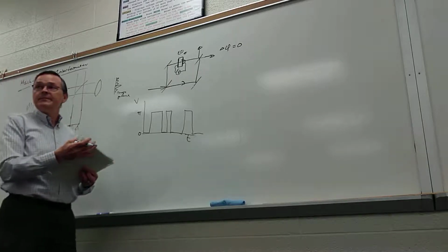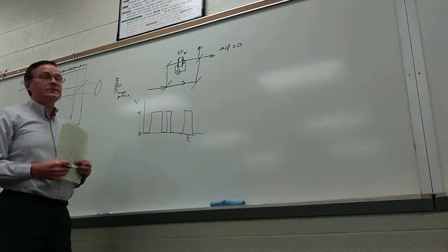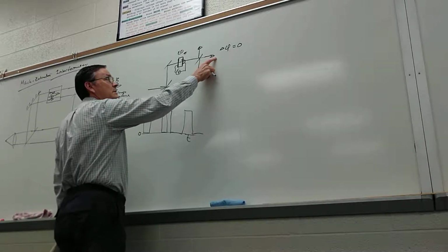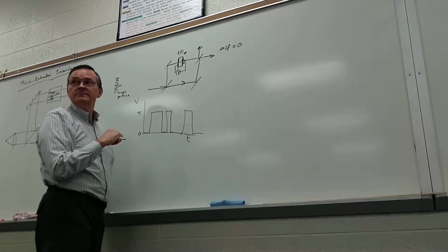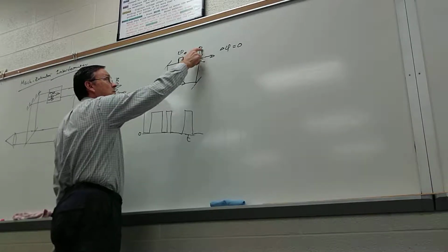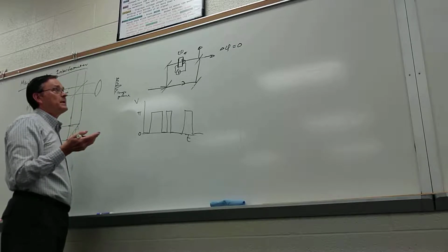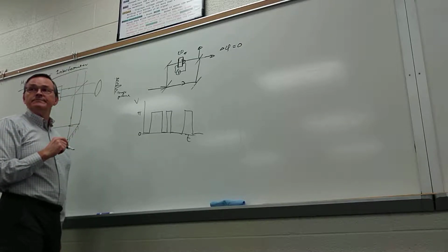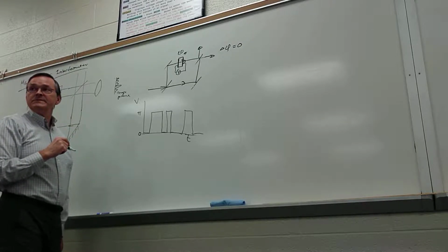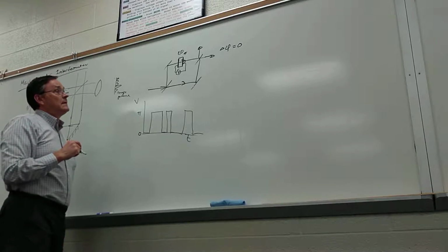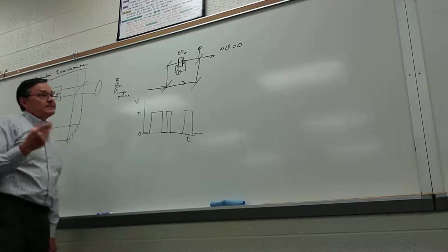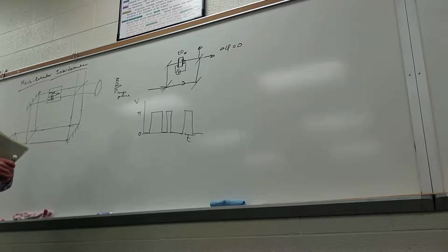Destructive interference. Destructive interference, so you have no light coming out here. So where's the light coming out? There. And so you just made an optical modulator. So if you want to modulate a beam you're going to put into a fiber for fiber optic communications, this would be one way to do it in a Mach-Zehnder.